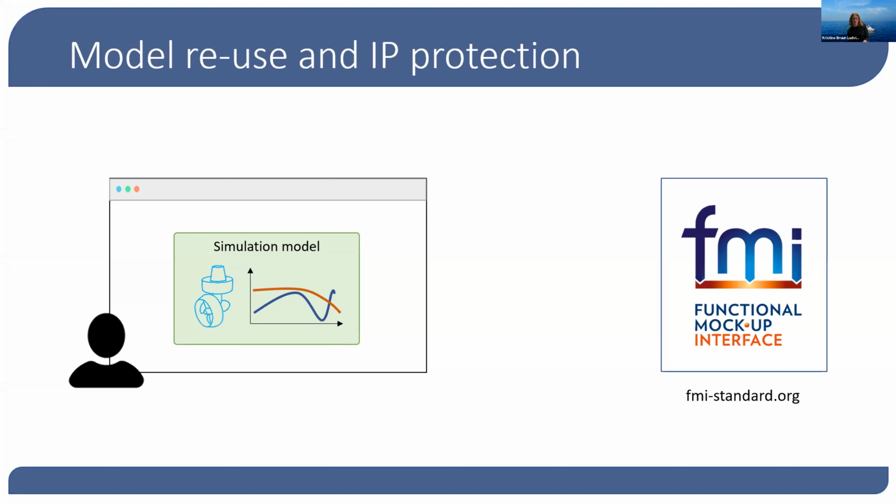For this, we have adopted the Functional Mock-up Interface as a standard for co-simulation. I assume that many of you are already familiar with it, and you can easily find the details online. It is a tool-independent standard for making submodels compatible with each other in a co-simulation context. It is completely open and free to use, and is supported by a large and growing number of tools. It also fits with our wish to make the Open Simulation Platform open to accelerate development.